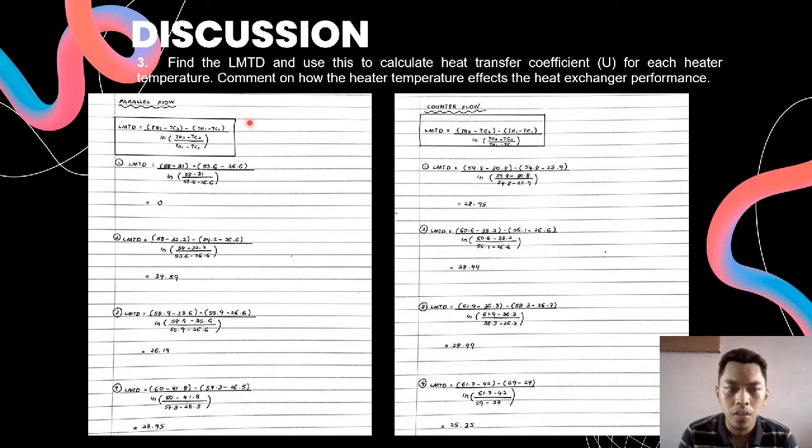So for the next discussion, find the LMTD and use this to calculate the heat transfer coefficient for each heater temperature. Comment on how the heater temperature affects the heat exchanger performance. So first, we must calculate the LMTD using the LMTD formula: (TH2 minus TC2 minus TH1 minus TC1) over ln (TH2 minus TC2 over TH1 minus TC1).